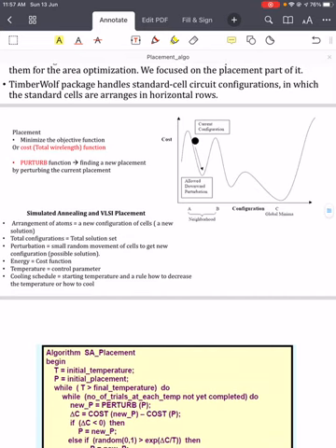We know how to compute this wire length when we have a set of blocks with defined pin locations and a netlist, and we know how to estimate the wire length of 2-pin nets and multi-terminal nets. We discussed different kinds of models in the last lecture: the RMST model, the RSMT model, and the half perimeter wire length model. We can use any of these models, sum up the lengths of all the nets, and define a cost function. Now we'll look at that in TimberWolf.